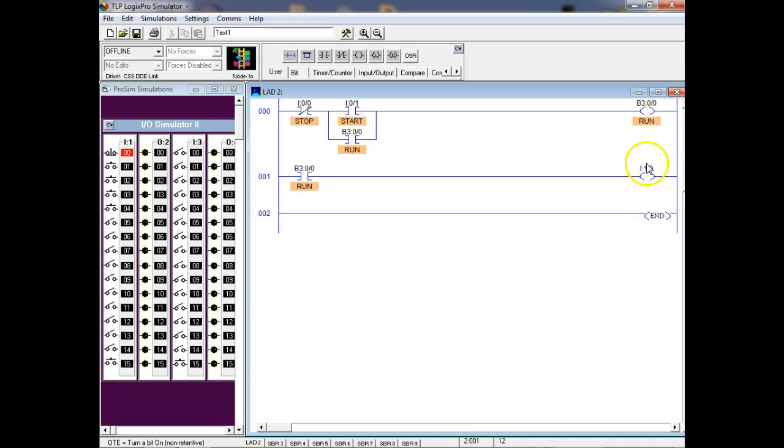Okay. So what we're going to do is go ahead and download this. I have a normally closed push button. And why are normally closed push buttons required for a true stop button? Well, if we break a wire, we need this thing to stop if we break a wire, right?